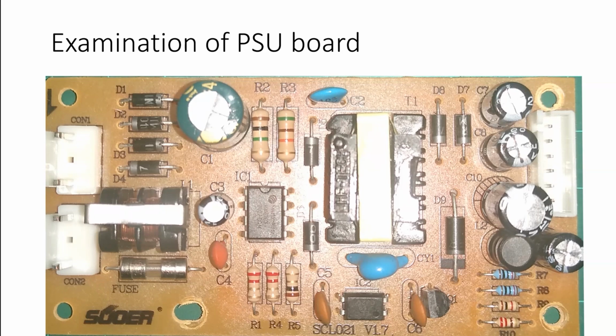Now we notice that we have the high voltage to low voltage transformer, which is marked T1 on this board and is vastly overexposed because of my rubbish photography, for which I apologise. Below it, there's CY1, which is a Y-rated capacitor, a high voltage capacitor for feedback of signals from the output stage back to the high voltage stage.